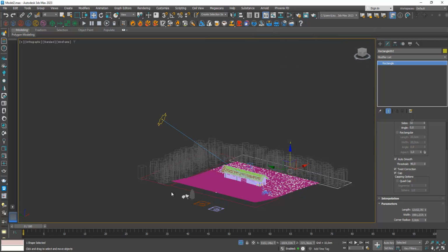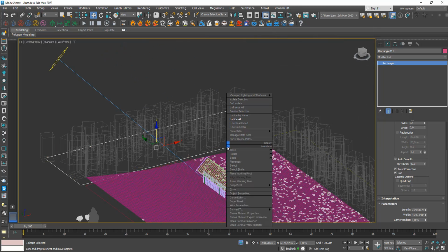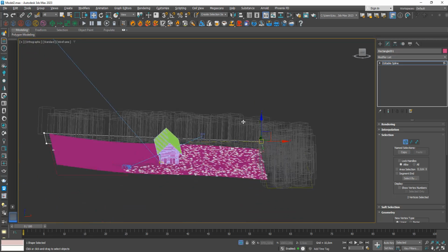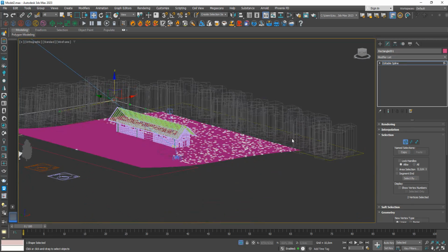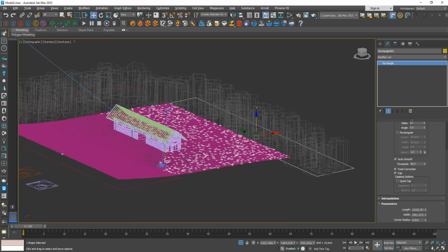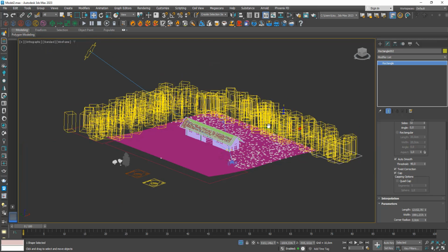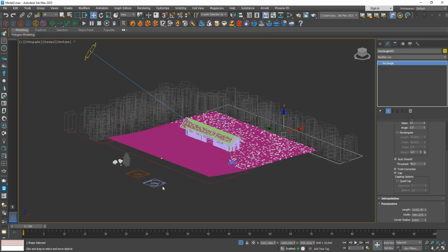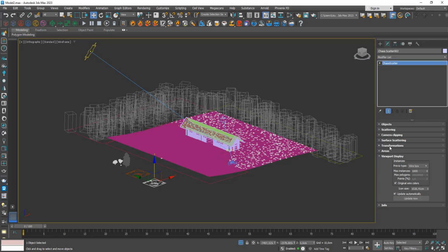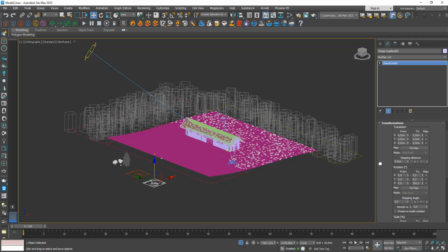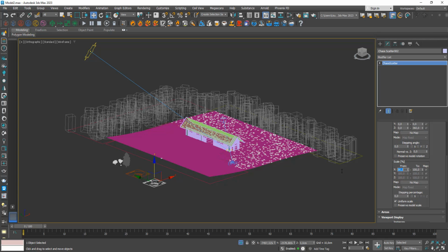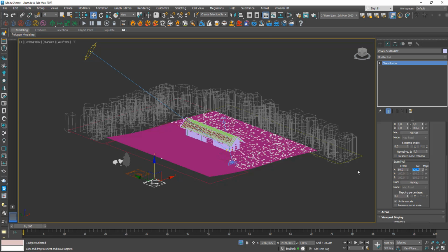So let's stop this interactive render, and we can turn this into an edit spline so that we can edit it further. I can lower the vertices from this side, and I'm actually going to be selecting all of the trees back here and lowering them a little bit more. Let's try that again. And also inside our Chaos Scatter, we are going to be needing to use some more randomness. So inside the transformations section, the scale from these trees are going to vary from 80% to 120%.